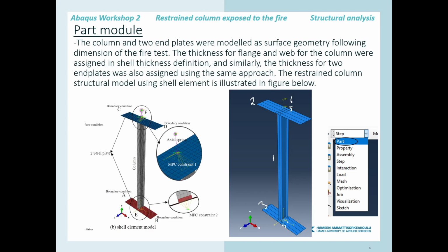Below that we will create another discrete point 50 mm below, and similarly we will create one 50 mm above the top end of the column, and then we'll assign a spring between these two points. Okay, so that's the idea for modeling the parts.